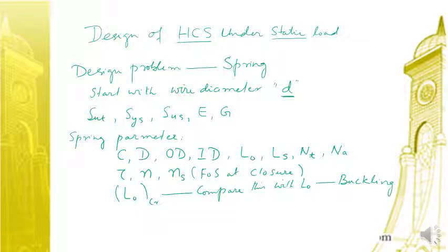We need to also determine the fundamental frequency, so that we can determine what will be the applied frequency. And the applied frequency is the fundamental frequency divided by 15 to 20. Better to use the parameter 20.